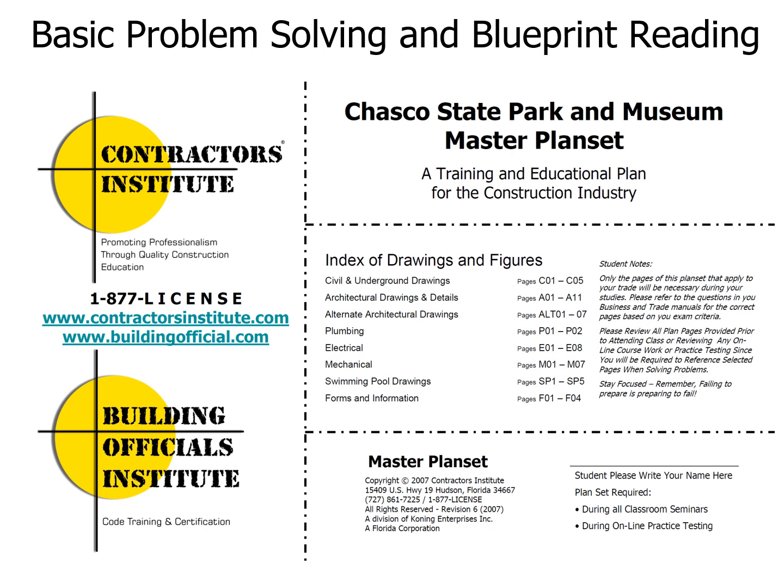In other words, if the page number starts with an A, you're in your architectural series of prints. If it starts with a P, those are your plumbing. Swimming pool, SP. So you can always tell which plan set you're in simply by the way the pages are numbered. Okay, and that's something important to look at.